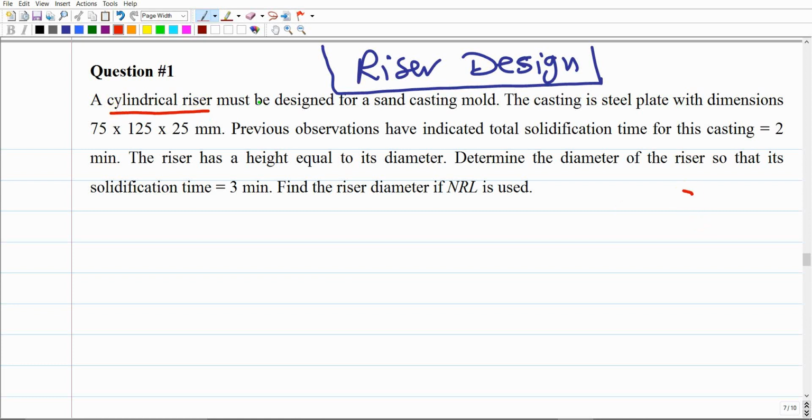should be of cylindrical shape, right? This should be the shape of the riser. And conventionally, the riser should have a cylindrical shape or a trapezoidal shape, like a tapered, conical shape, or any other shape. It is not necessary to be circular. It could be square, or a rectangular base with an extension like a pyramid shape, for example.